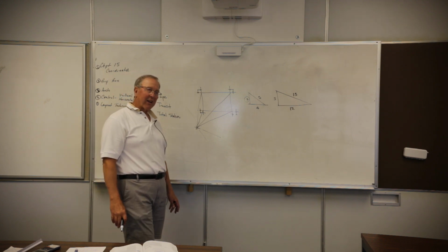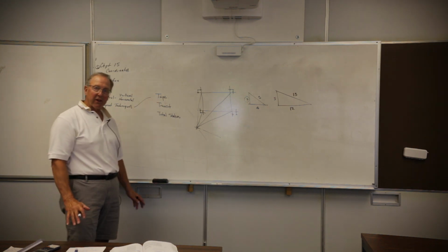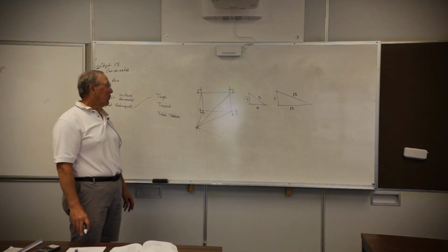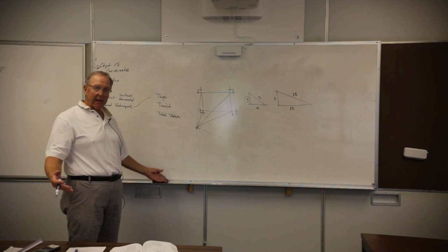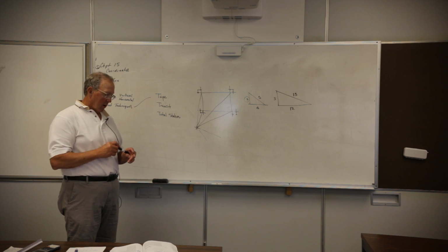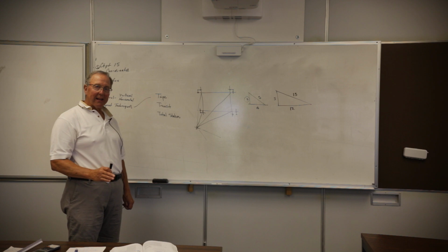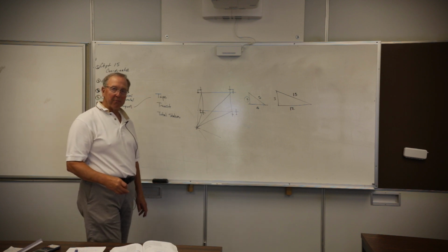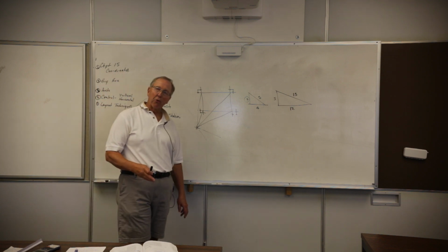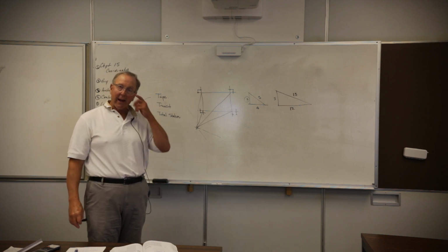So our layout techniques are varied. They're project specific. They're also equipment specific. If you don't have a total station, that takes that out of the mix. So when you lay stuff out, make sure that you pick a technique that makes sense to the people in the field who are going to be using it. You're not laying this out for you. You're laying it out for the least skilled person in the field that's going to be building it. They've got to understand it.